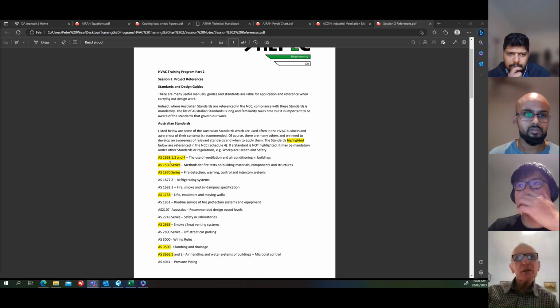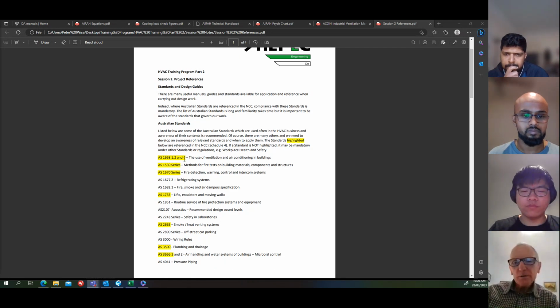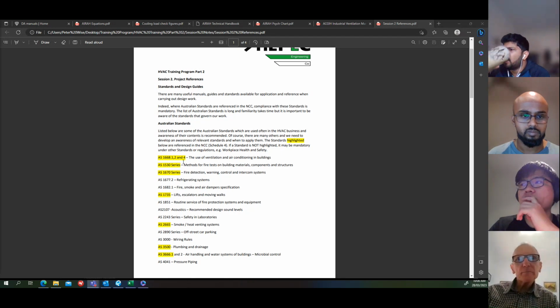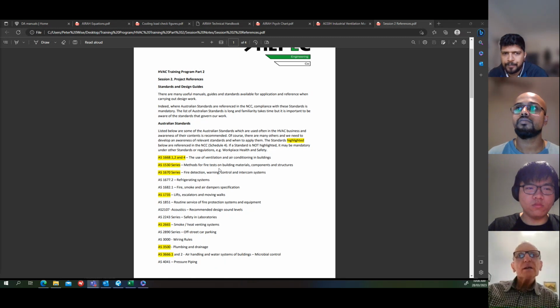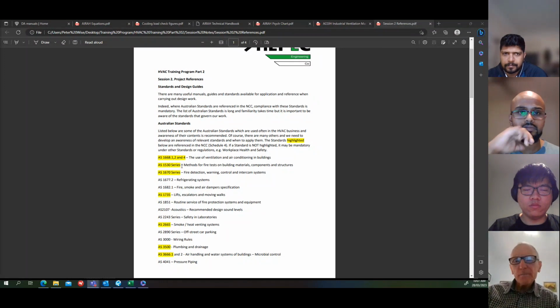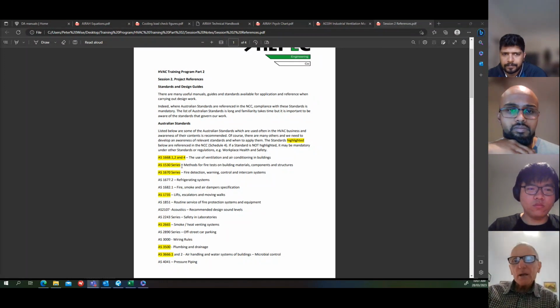So AS 1668 Part 1, 2 and 4, we've talked about those last week. Everybody's aware of them. You use them every day. AS 1530 series, methods for fire tests on building materials, components and structures. This is the series of standards that deals with testing fire dampers, fire rating.